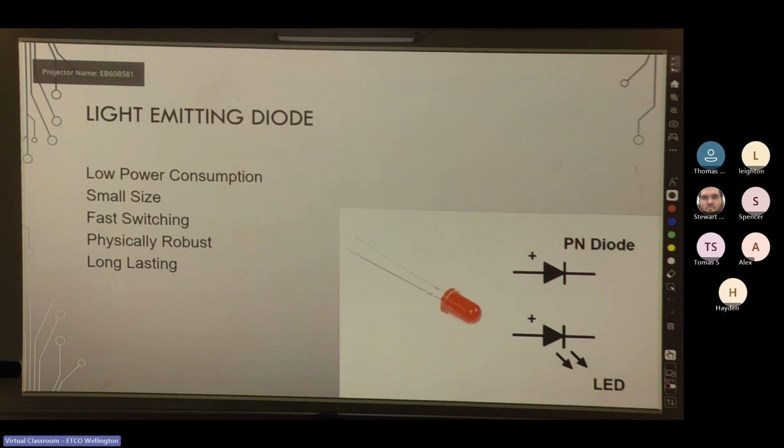Good guess. So basically, with the 50 hertz flicker and the machine rotating based on the 50 hertz frequency, an object in, say, a lathe or a rotor on a motor may appear, instead of rotating, to be stationary. So that it looks like the machine's not spinning when in reality it is. So that means that potentially someone could assume that the machine is not operating and then be less cautious around it.